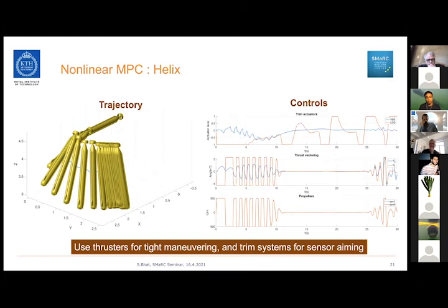By doing all of this, we could find that in all of these cases, the control goes between maximum and minimum values. And we call this bang-bang control. And in the field of optimal control, in many cases for these kind of systems, bang-bang control is the optimum. And it's normally very efficient to do that because then you don't change the control much. You just apply a force and then you stop applying the force and then it's supposed to just reach that set point.